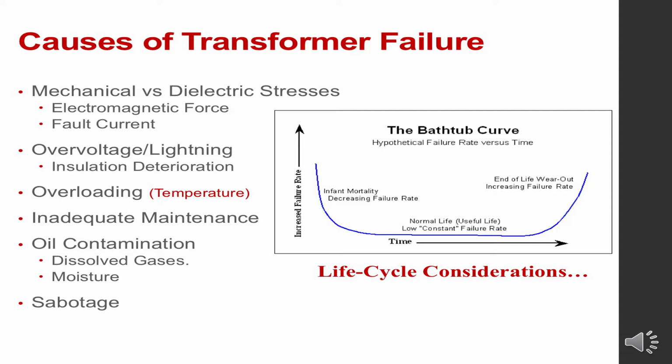That meant the transformer ran hotter than the nameplate value. A neighboring utility that we used to go and help out in an ice storm would fuse their transformers at 300% of full load. So the transformer was boiling hot on the pole by design, and what they were apparently doing is accepting the shorter life cycle of the device, using a smaller unit to feed a larger load, so to speak. So overloading can happen accidentally, or it can happen by design.